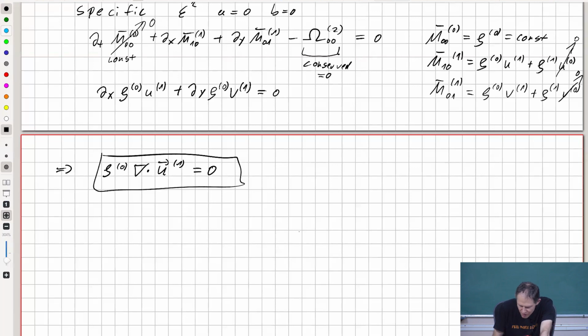Okay? Now, this is the first equivalent PDE that we observe, and we observe that this is the incompressibility condition, and we see that under this scaling we get the incompressible version of the Navier-Stokes equation out. So the first equivalent partial differential equation we got.